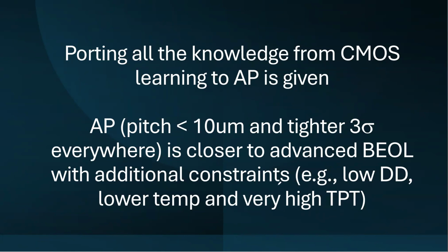What do you mean by that? Well, you need a very low defect density, because anything you connect together is very expensive. If your interconnects are dirty with a lot of particles, you're going to lose the high value parts you put on.